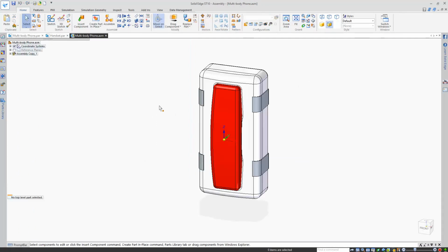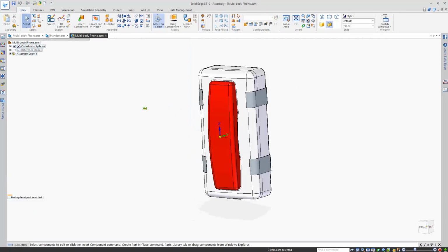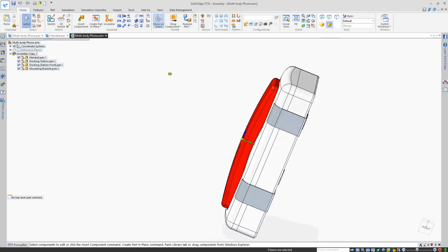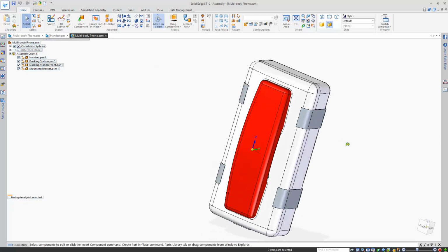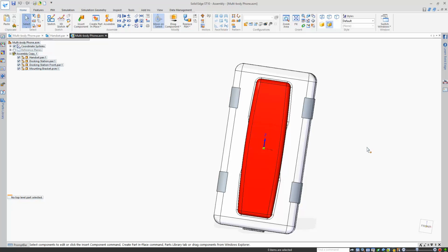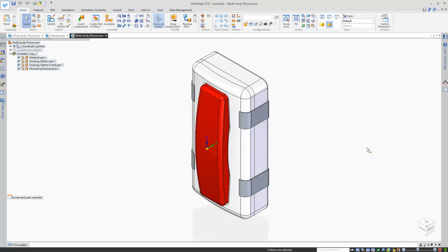You'll notice when we do so that there's an assembly copy in here, which also links directly to the part file to obtain the positions of the bodies. That means you can't move these bodies around with normal assembly commands, like the steering wheel, which, when we select something, doesn't show up. Once the assembly and parts have been saved, though, this assembly can be drafted, parts can be assigned their materials and other attributes, and a parts list can be generated for production. And all of this achieved while keeping all of your geometry in one file.